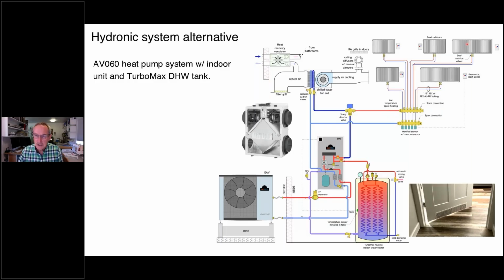And just to keep everything electrically controlled, we're showing thermostats here. So these thermostats would come back to valve actuators on the manifold. This hardware is available from dozens of suppliers today. It's readily available. Here's an example of a heat recovery ventilator. You can see there's 4 connections on it. Basically, 2 of those connections are the outgoing stream. 2 of those connections are the incoming stream. There's a couple axial fans that drive the airflow.